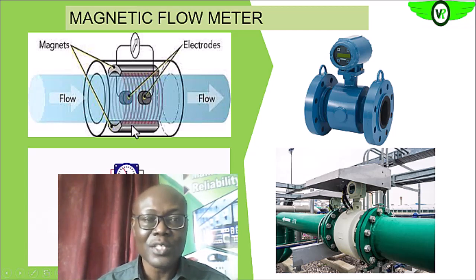So we'll say the magnetic field created by this permanent magnet, these are the magnetic lines of flux. As the fluid is flowing through, you see these electrodes, the fluid will momentarily at that point complete the connection, and since voltage or electric current has been induced in it, it will run through this circuit, because it will at the end of the day close the circuit, and then you have your reading.